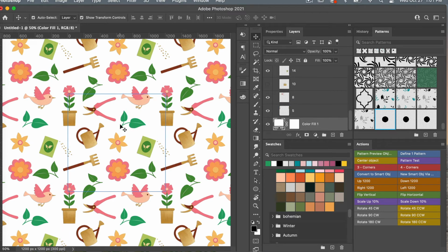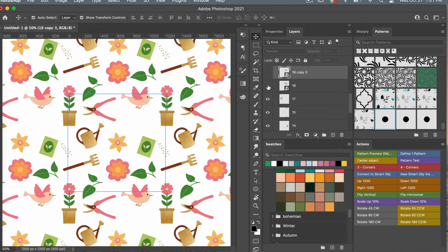And now you have another instance of that leaf, but you are now able to manipulate it independently of these other two leaves. So this action is good in instances where you are making duplicates, but maybe you want a different color variation for the second object. So let's go ahead, we'll turn off this leaf and bring back the original one here.